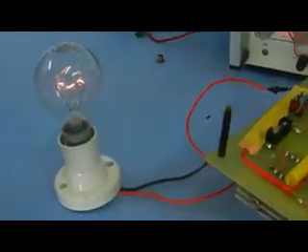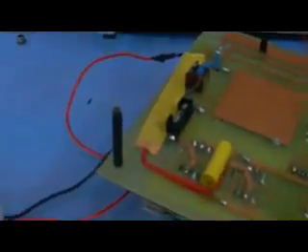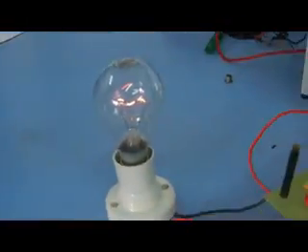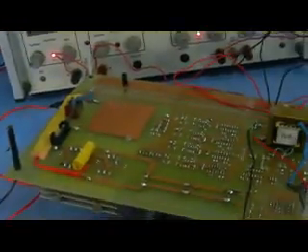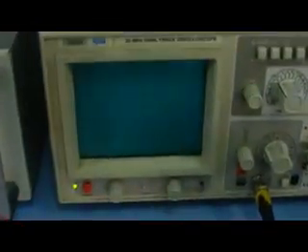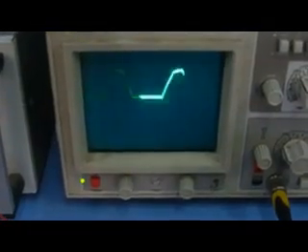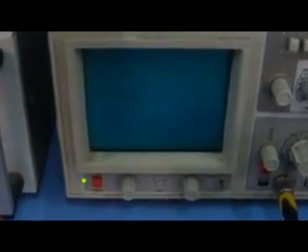We will now explain the concept of our project practically. Here on our board at the load side, initially we have a lamp connected with a diode which makes it a non-linear load. When we observe the source current on the CRO, we see that the source current is a clipped waveform that is actually full of harmonics and which is harmful to the system.